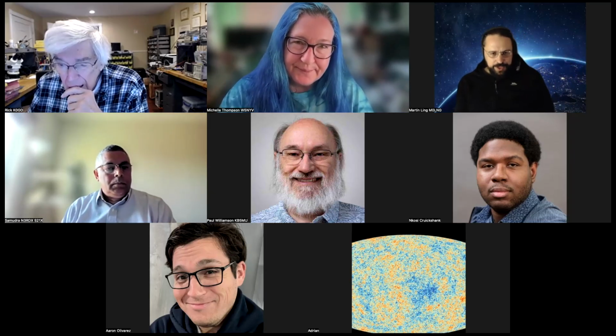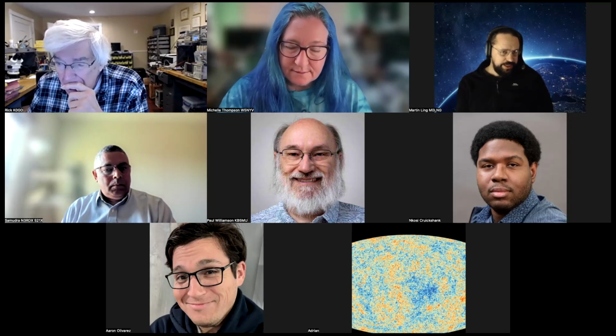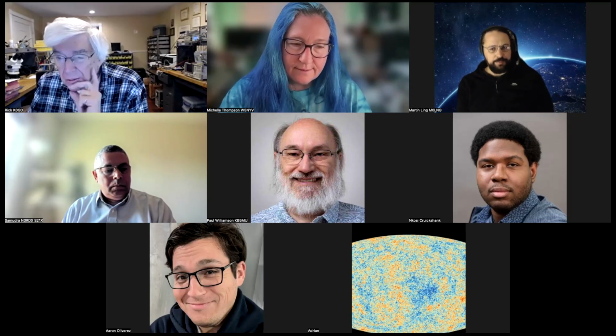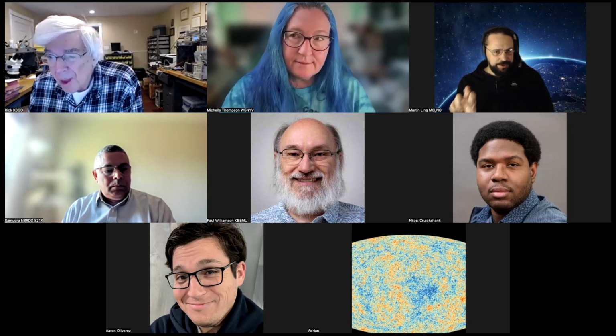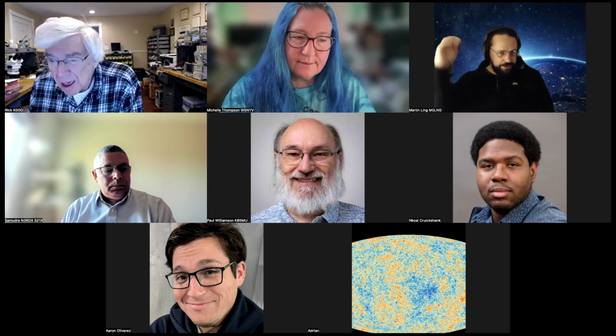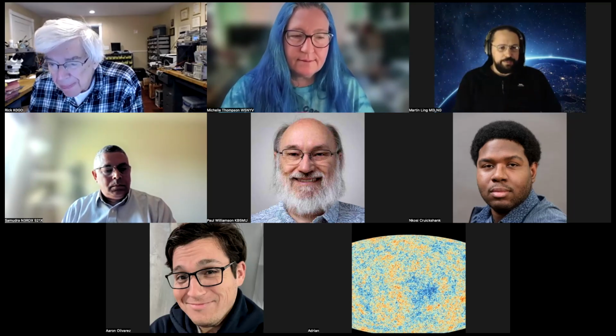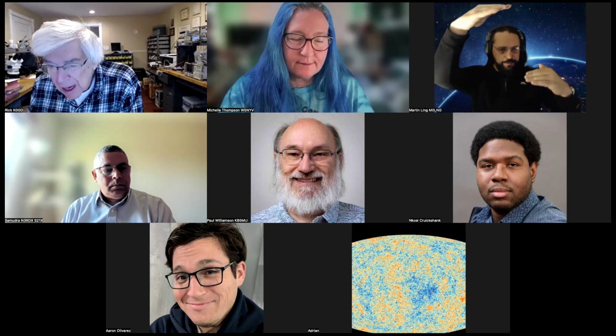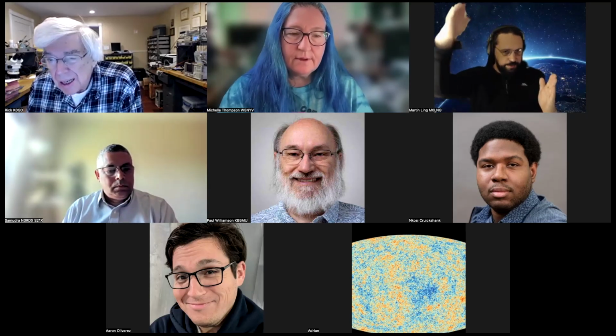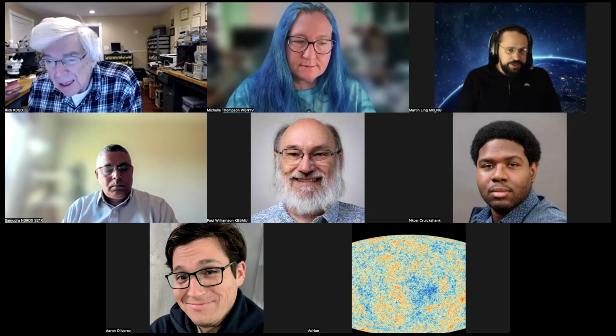To answer very briefly, that's kind of why I had this focus on the dynamic range of this and tapping this off before we go into the AGC that's part of the linear transponder path in this satellite design, and coming in with an ADC path with plenty of bit depth, so that if you've got someone at 100 watts and someone at 5 watts, you're what, 13 dB apart at that point, right? You've still got enough bit depth to be able to pick out those two signals, provided they're reasonably spaced in frequency and one's not splatting onto the other. That's viable.